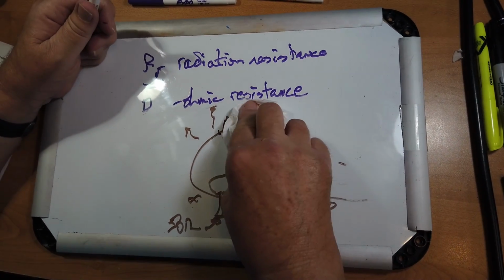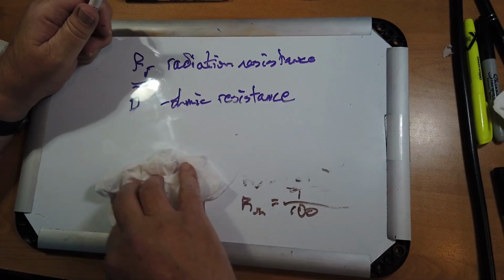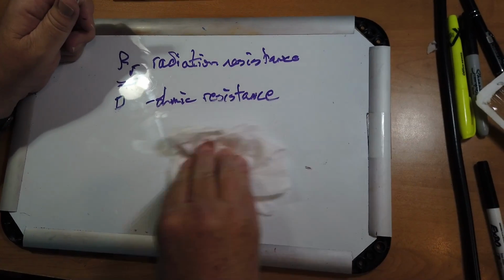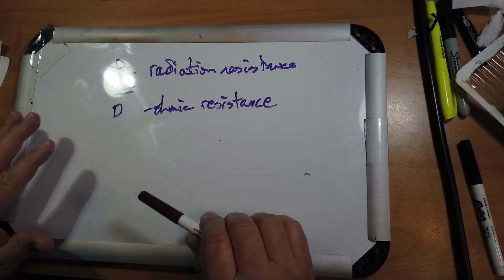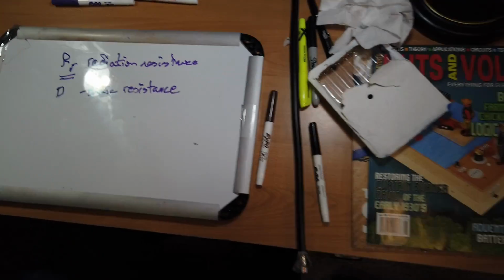The MFJ loops and some other loops that I've seen actually use aluminum pipe or copper pipe even, and do what they can to make sure that the ohmic resistance is as tiny as possible. So I hope that helps give you a few of the design considerations for mag loops.